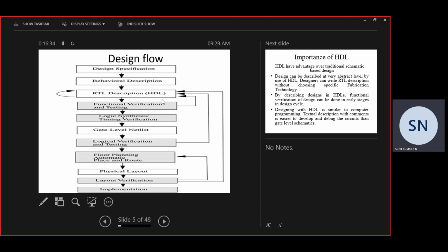After that, we should have parentheses. Within this, you have to define all the inputs and outputs. Whatever is inside the structure, no need to bother. If I am going for a full adder, I am not considering internal connections, such as the output of the first XOR gate being connected to the second XOR gate's input. I will only write what all the inputs and outputs are. Intermediate connections we are not going to write.